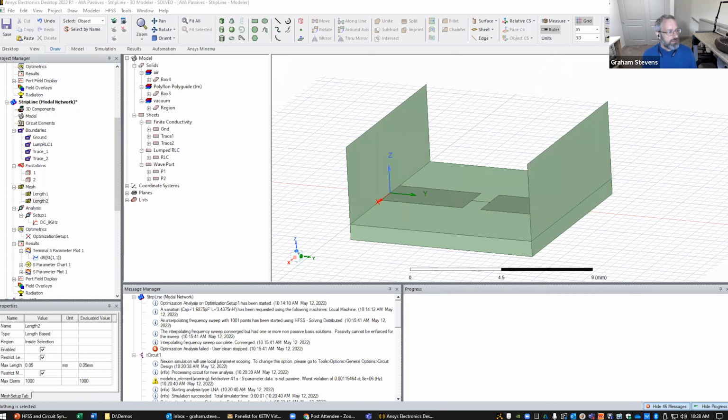Somebody says, I'm confused by the fact that your HFSS linked element in circuit is 3 ports. In my mind, to recreate this situation, there should be 2 HFSS links with the LC components linking the 2. By putting those values to ground, you're assuming symmetry in the model. Is that safe to do?